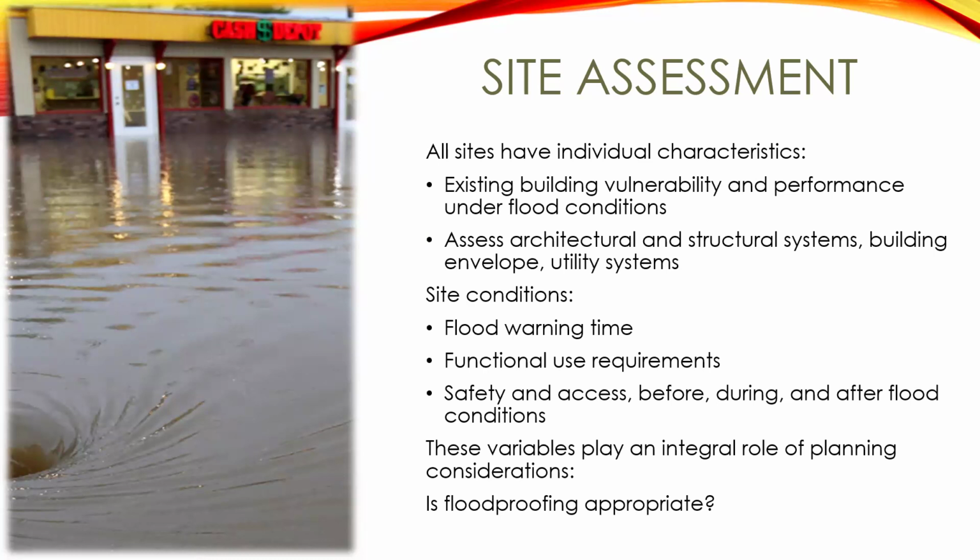You have to look at the flood warning time, any functional use requirements, safety, and access before, during, and after the flooding conditions. That is going to play an integral role on whether you can even do the dry floodproofing or if it's just going to need to be elevated.